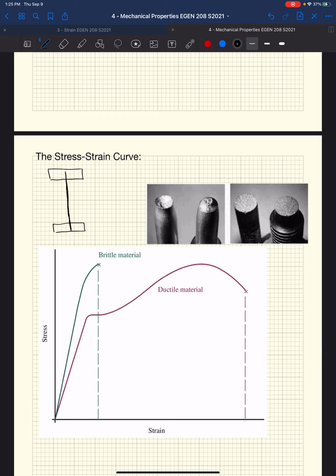between two plates. And you anchor it to the 2 plates, and we kind of saw this in our chapter 1 discussion on stress and shear stress, where we had 2 boards that were glued together and we were pulling them apart. That's essentially a tension test. You take a specimen of a known material. In this case, maybe you wanted to take steel of a certain steel grade, and you wanted to pull it apart. And so we take a piece of this material of a known diameter, and you can see 2 specimens there on the right. Those are pictures of them.